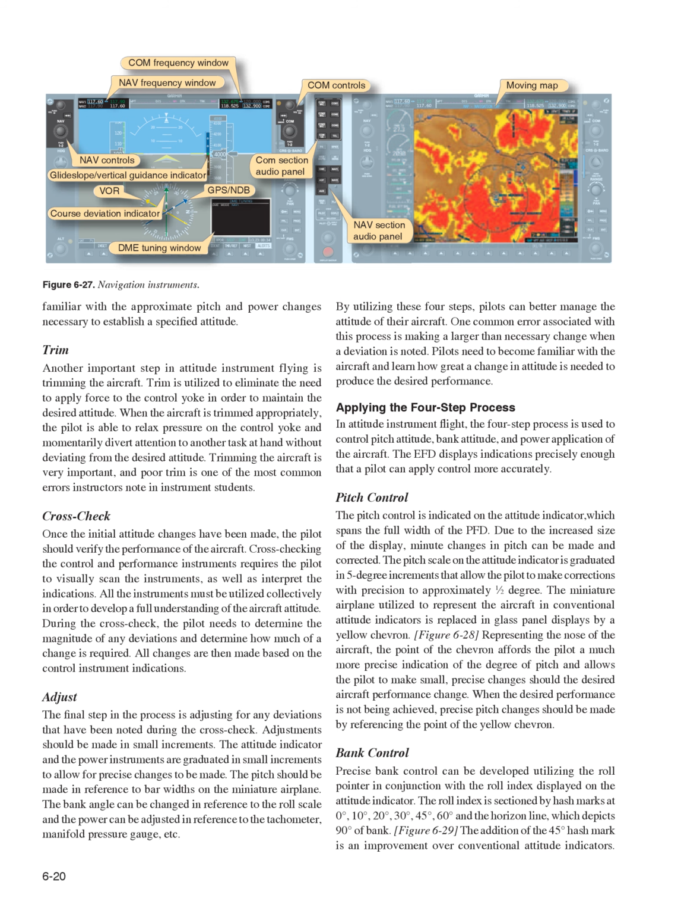One common error associated with this process is making a larger than necessary change when a deviation is noted. Pilots need to become familiar with the aircraft and learn how great a change in attitude is needed to produce the desired performance.